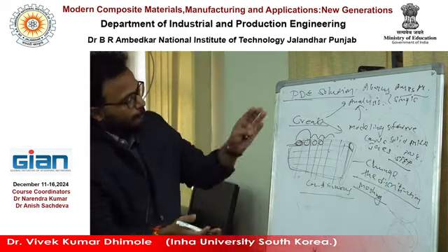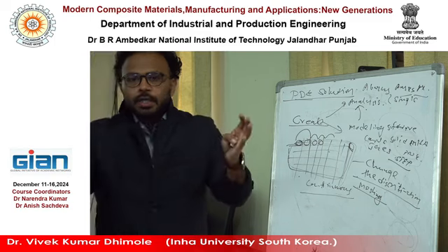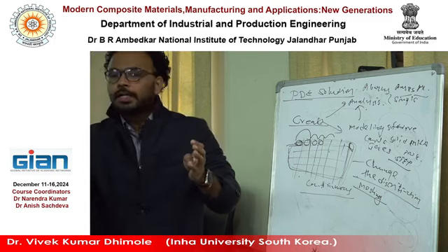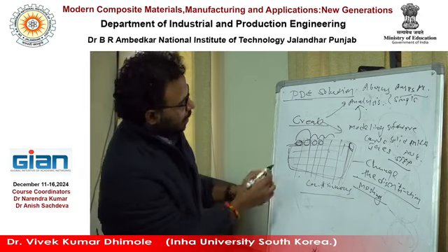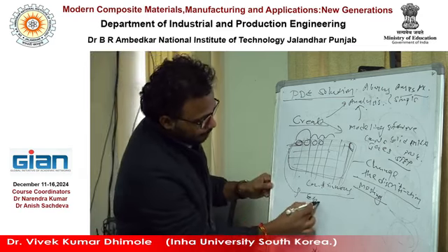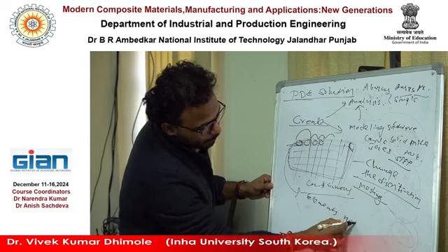Then after importing, what is the purpose? It's a physical model, a continuum model, a continuous model. You have to make a discretized one, right? Then, after discretizing, you have to make a mesh. Meshing means you have many elements, and each element has nodes, right?